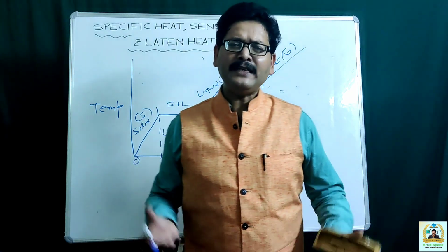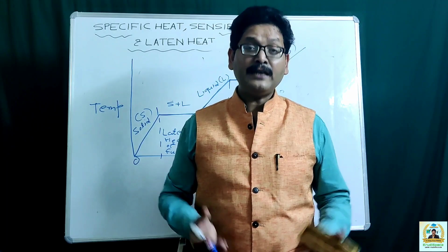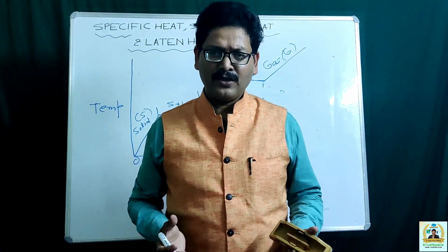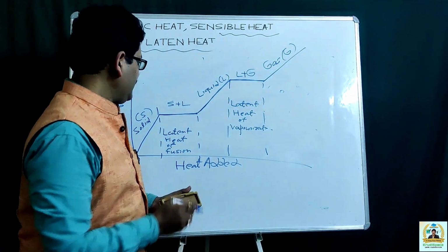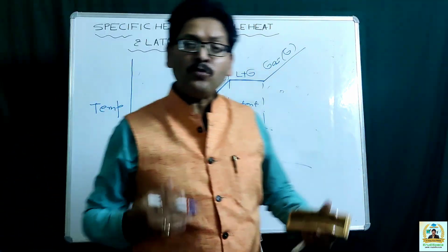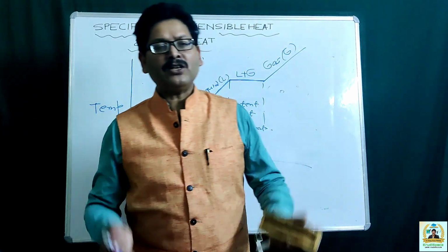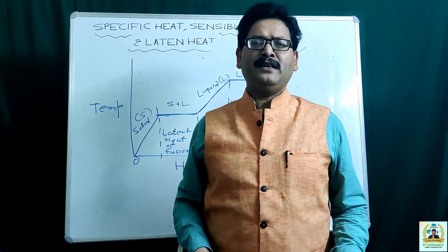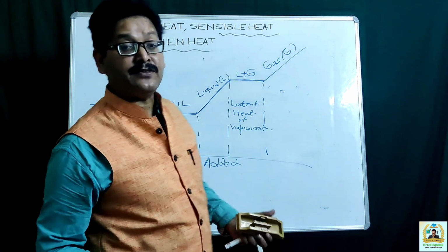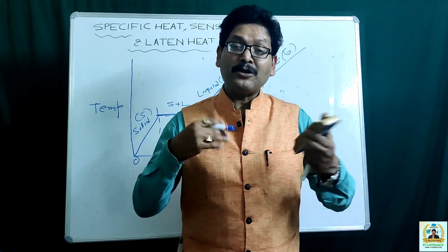We know that in sensible heat addition, the heat addition is associated with rise in temperature. That is something you can sense. You can measure the difference in temperature when heat addition is taking place. Then this is actually your latent heat addition. So here what happens? Heat is added, but this heat addition is not associated with any rise in temperature. This heat energy is actually utilized in converting the solid state into liquid state.